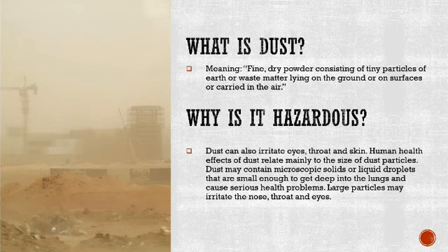Well, the meaning is fine, dry powder consisting of tiny particles of earth or waste matter lying on the ground or on surfaces or carried in the air. And now if you take a look on the left hand side, there is a construction site with a lot of dust on it. Now we have to do dust suppression obviously when we get to a site, and this is when those huge water trucks come around, and often throughout the day at the start of the morning they are pumping out water in order to suppress that dust from constantly being raised. And this is because of tires that are driving over it, people that are walking and also working in the area, and then possibly even plant or machinery moving in and around the area.